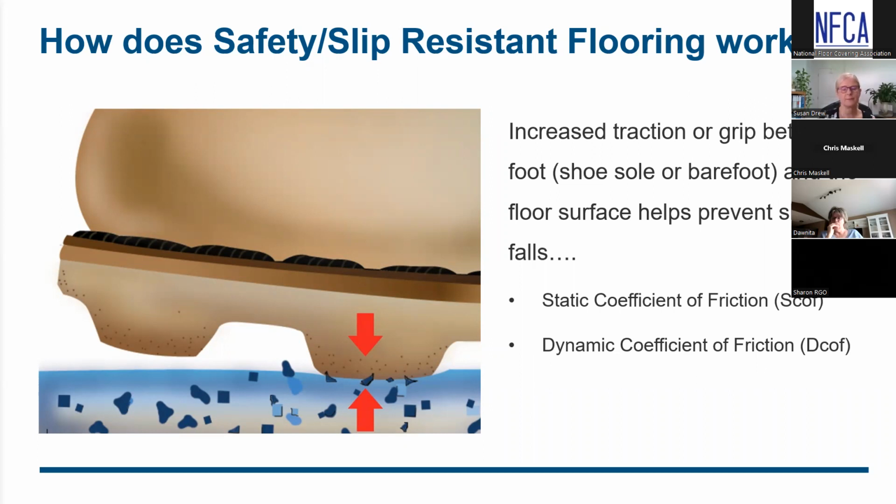So the grab is a combination of the protruding particulate and the extra resilience in the material, the softness of the material. And I won't just say protruding particulate, because you can have slip resistant materials where all of the aggregate is inside the material itself, but when you step on it, it gives and that aggregate comes up and creates resistance. So it's not protruding on the surface all the time. So it makes it easier to clean, but still slip resistant. Right. So it goes to work when it's at work. When it's needed. Exactly.